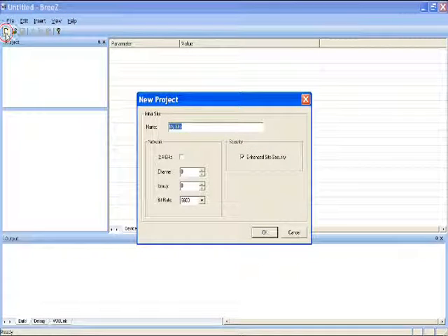Then we will start a new project, and we will name it. Today I will name it Analog Test. The 2.4 gigahertz checkbox is for overseas hardware only. The channel availability is up to 9. The group availability is up to 999, giving you many options. Set as you wish, but we recommend you dial away from each other if sites are closer than 2,500 feet.